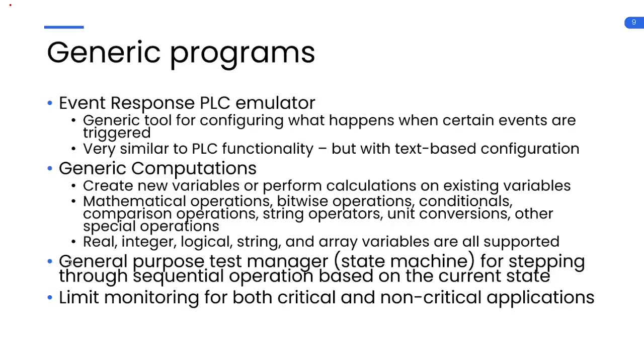Let's see, so then we also have a general purpose test manager. Some people would refer to this as a state machine, but if you have some sequential operation that you need to do certain things based on a certain state of the system, then this is a program that we would generally use for that. So a lot of times we're using this for turning on dyno drives where we use the term mode to refer to these states.